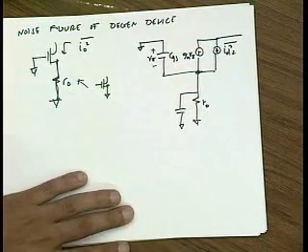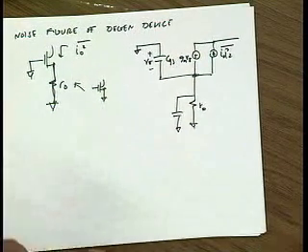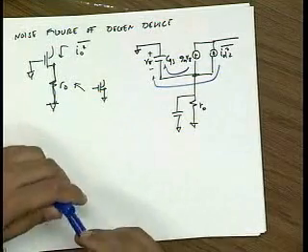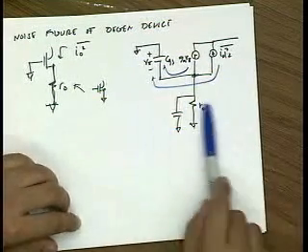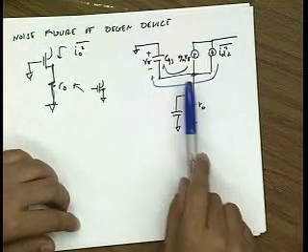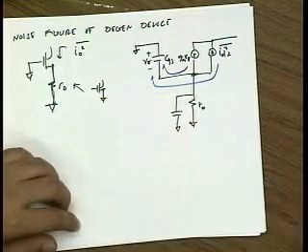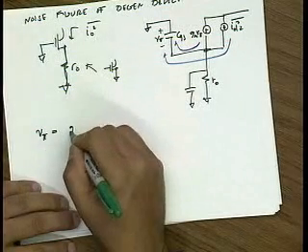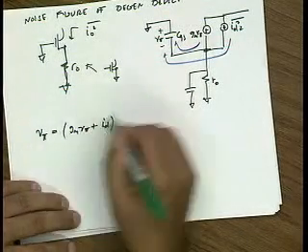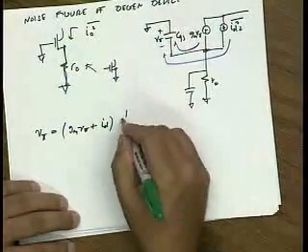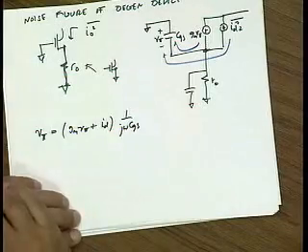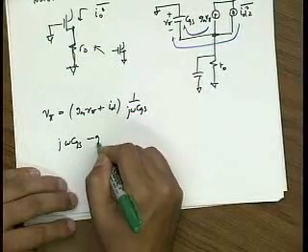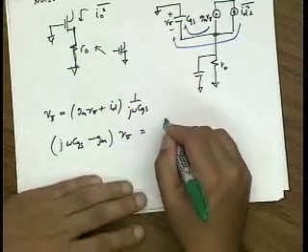Okay. So let me assume that at low frequencies, all the current actually goes in this direction. Why is that? Well, because this is a very high output impedance, right? Let me assume that the output impedance here is much larger than the impedance here. Okay? Just a simplifying assumption. You guys can go home and do the full-blown analysis. In that case, V pi is GM V pi plus the drain current noise, these two noises, times 1 over j omega CGS. Okay? There is no current divider. All the current goes there. Okay? So a few lines of algebra, j omega CGS minus GM V pi is equal to I drain.